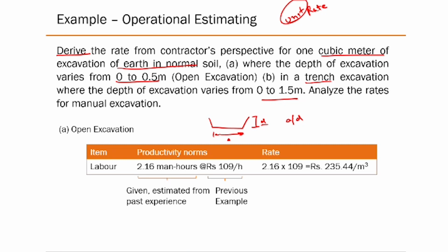So in that case, you don't need to worry about preparation of the soil, or about putting some sort of formwork to make the soil stable, because you expect that it is not going to cave in. What happens in excavation is, because of the overburden pressure from the surrounding soil, this kind of caving happens, and that's a safety hazard. Your work will also not be effective, because the material is going inside again.